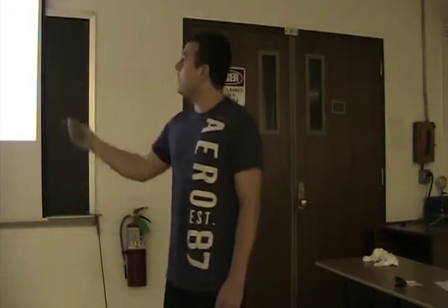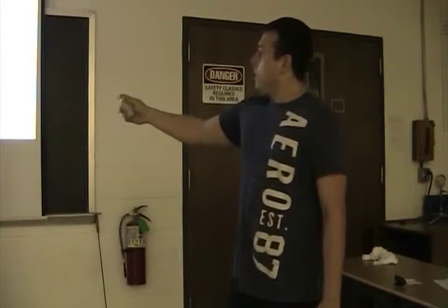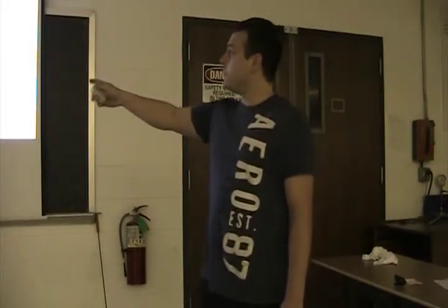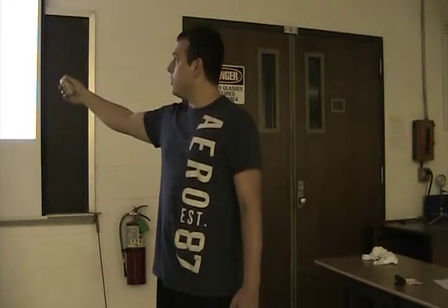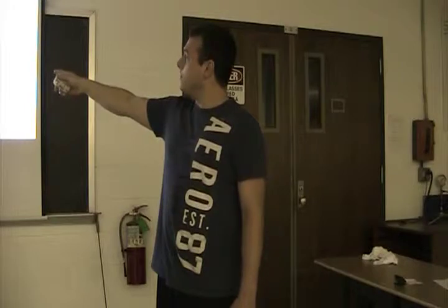Here are the flow regimes for your nozzles. If you look over here, you have a subsonic. Basically, it's saying that in your converging nozzle, your Mach number is going to be less than 1, and also in your diffuser. Whereas with your supersonic, as your nozzle converges, the speed approaches Mach 1, and in the diffuser, as it leaves the throat, it's going to accelerate past Mach 1.